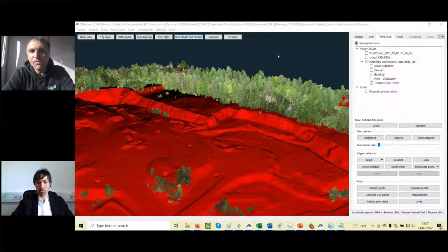And it's good to know that if you don't have an RTK drone and would like to upgrade to a PPK solution, we tested the solution from Topodrone and it works really nicely. It's super accurate. If you do a double grid, the quality is super nice, also with a minimum of ground control points. So you have this option.